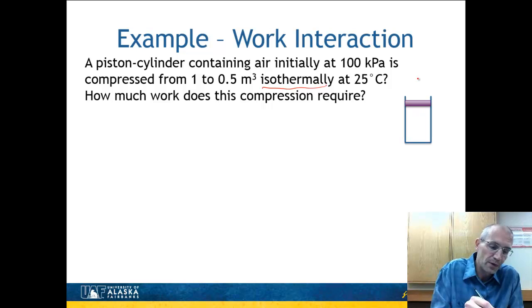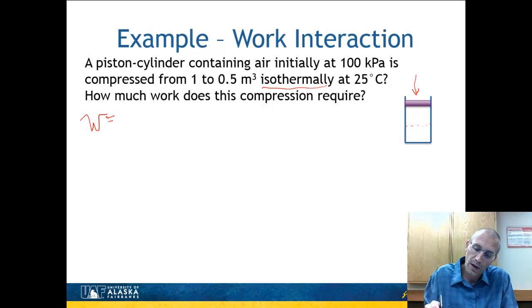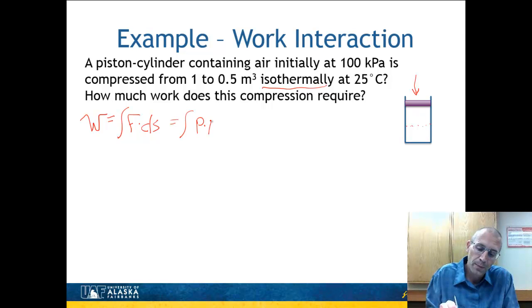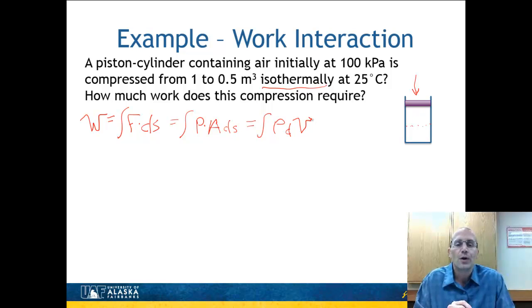Here on the right, I show a piston. We're going to exert a force there. Its final state is going to be 1/2 of the volume. Assuming that this piston is tightly fitting, all the material will remain inside the cylinder, which means the pressure will go up. So here we're going to, again, calculate the amount of work. We know that the work is the integral of a force through a distance, and the force is pressure times area through that distance. So this becomes the integral of P dV. Often you'll hear compression work called PdV work.